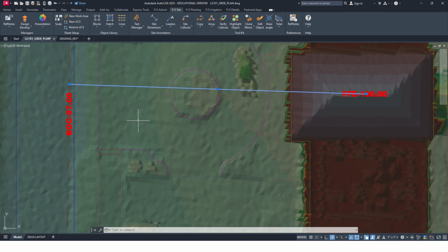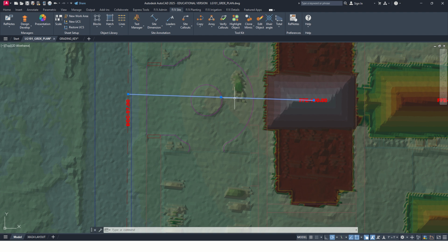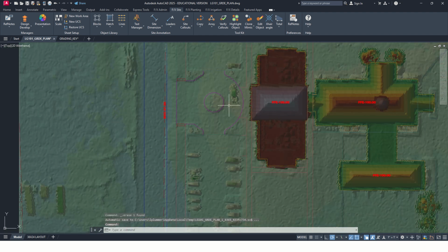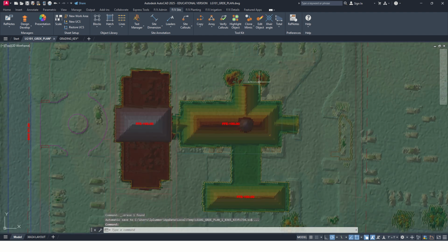That's excellent, because the rule of thumb, and it's a very important rule to follow, is that 20 feet from any structure needs to be graded at a 2% slope away from the structure. Remember, you always build your house on a hill. So the watershed's on.